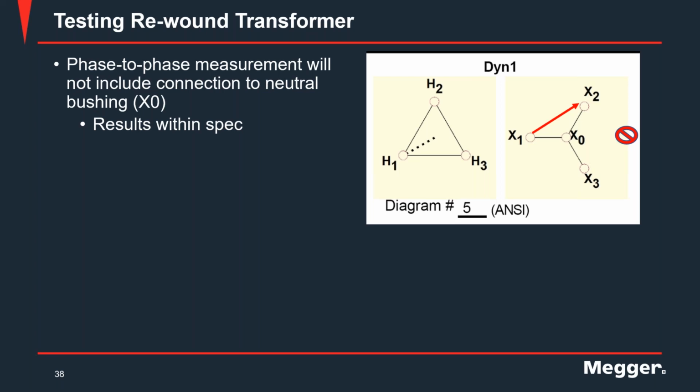Like in our case, that rebound transformer might have a slight mismatch. That could be the normal state of that transformer. That may not necessarily mean that the transformer is degraded or has issues with its winding, but having that data point and comparing with historical data will become important there. So that's why you want to have some historical information or factory information that you can compare to.